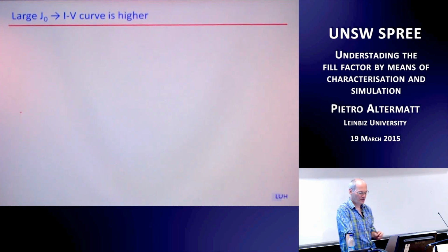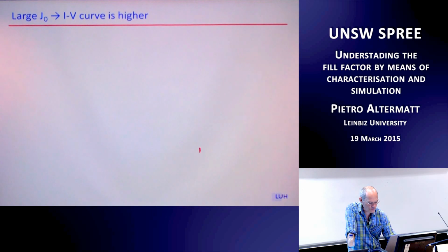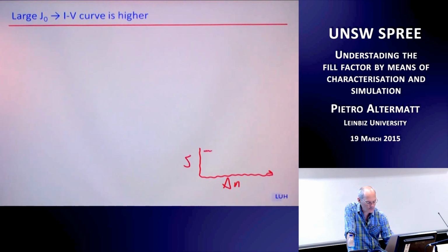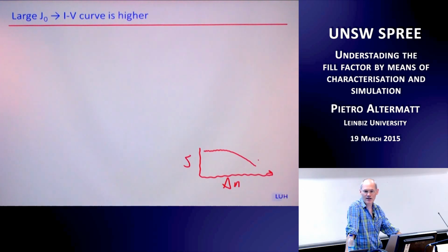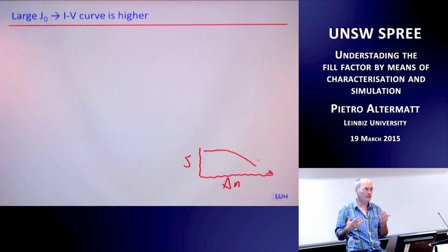Let's say you got a cell that has a surface recombination velocity as a function of delta n, say delta n and S, and usually it goes down a bit. Depends a bit on your charge, on your electrostatic conditions, etc. But you're probably familiar that surface passivation may be injection dependent. Also bulk lifetime may be injection dependent. You've got actually quite a few sources of injection dependency in modern PERC cells, for example. So this is quite a modern topic.